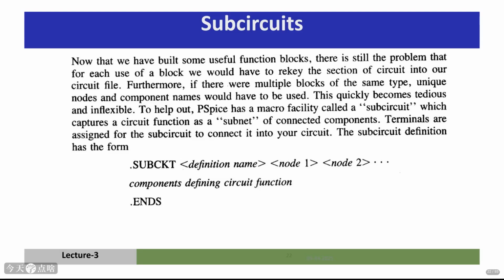Imagine you've designed a really neat little function block, like a square root calculator. You'd hate to have to redraw it every time you wanted to use it in your main circuit. That's where subcircuits come in. It's like creating a reusable macro or module. You define your subcircuit once, giving it a name, and specifying which terminals connect to the outside world. Then, you can use this subcircuit multiple times in your main design, just like using a pre-built component.